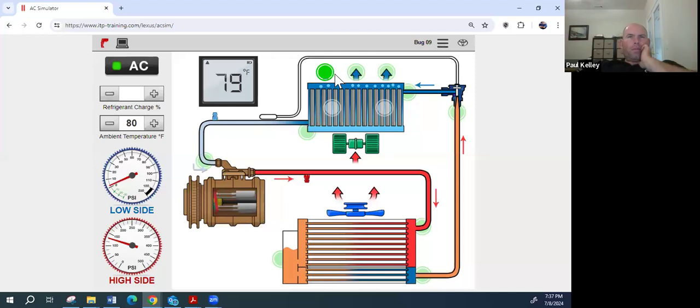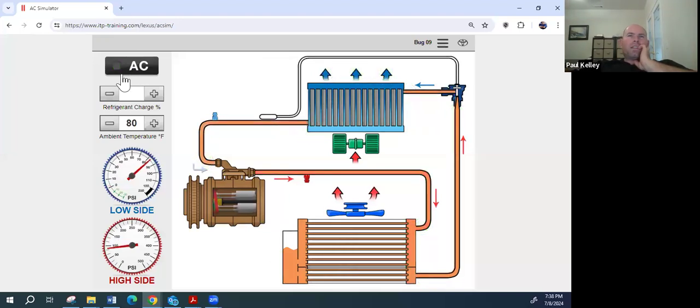That AC's a no-go. Now what do you want to do? Just think about it. Consider it. Weigh it out. Go over the possibilities. How about we check the static? We got about 88 PSI on an 80-degree day. What do you think? Is that under or overcharged?